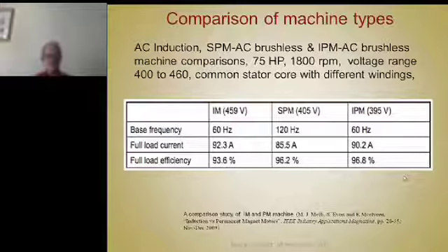It gets a reluctance torque. The IPM is really a hybrid between a PM synchronous machine and a switch reluctance synchronous machine, because it gets a reluctance torque, and that's why the full load current is almost as high as the induction motor, because you had to have extra current to magnetize the salient poles, and that was done effectively by using power to saturate part of the magnetic circuit around the magnet poles, to force the torque through the saliency part of the poles.